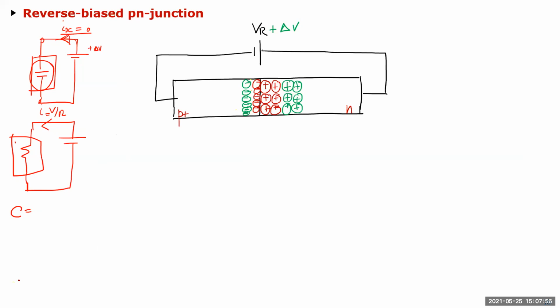By the way, when I explained capacitor, this was taken for granted. I didn't say it, but obviously everyone knows that Q equals CV. So if I want to find out the change of current flowing through a capacitor for a change of voltage, then you basically differentiate both sides. If the capacitor is a linear element, then it is C times dV over dt, right? So exactly. Abhinav, I think you got it right.